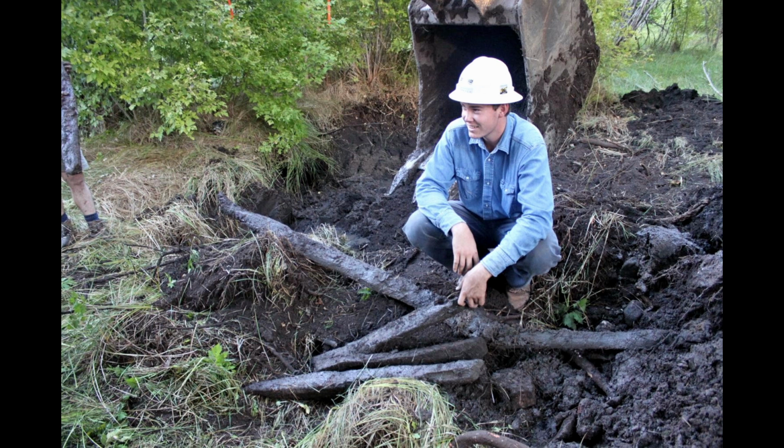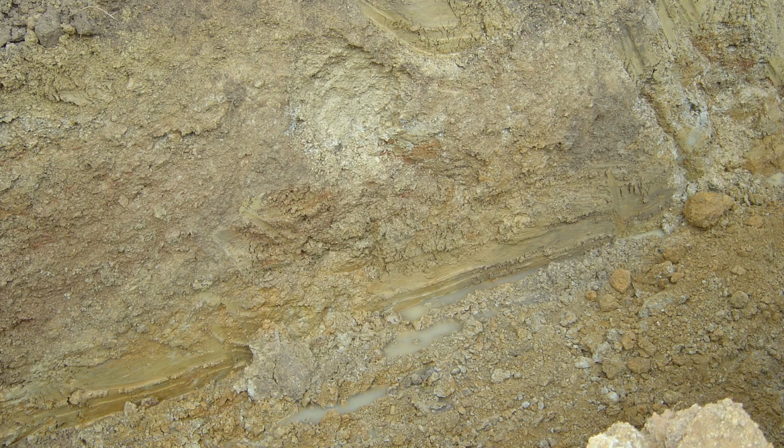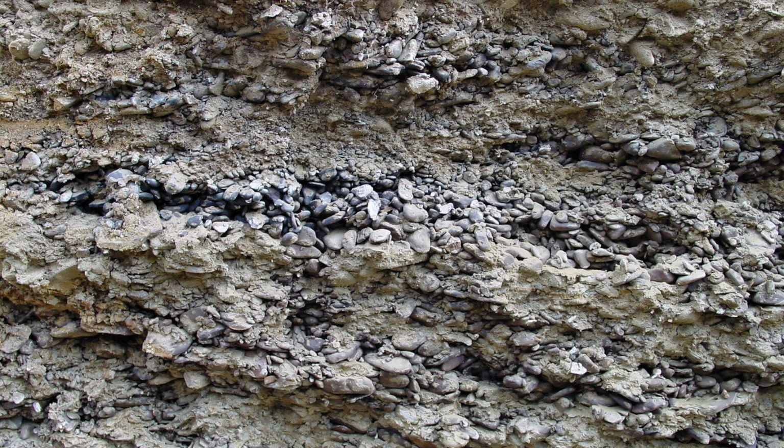Here's a buried drainage structure we uncovered while building a groundwater dam in the desert near Portal, Arizona. This wooden drain would have caused the wetland we are building to fail had we not dug the core trench for the groundwater dam. You can see water collecting in the bottom of a core trench that we dug for building a groundwater dam. The water is flowing out of a hole filled with loose soil in the side of the core trench. This hole may have been made by someone using a mole plow to drain a wetland years ago.